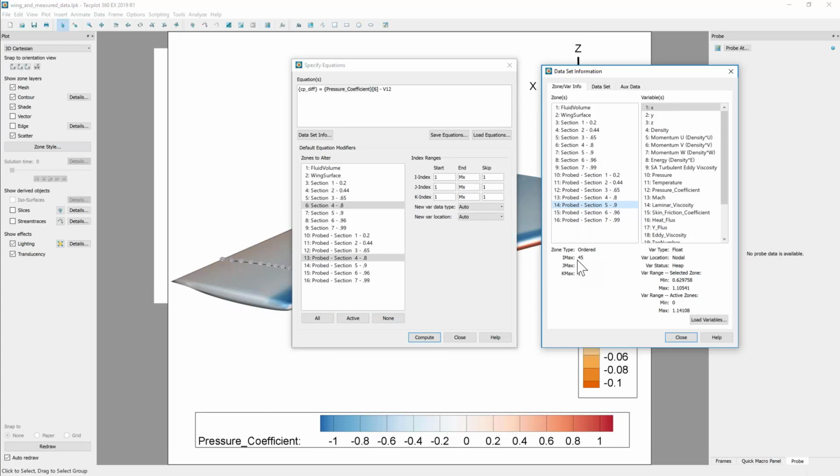If I save Tecplot data for a different time in a different Tecplot file, can I extract polyline data over the different Tecplot file? So if you have multiple files, I'll try to answer the question as best I can. Yes, from a script, you could certainly load one file at a time and automate the extraction with a Tecplot macro. A macro can be written such that it will place the polyline and do the extraction, and then you could write that extraction to a file, and automate that for all files.